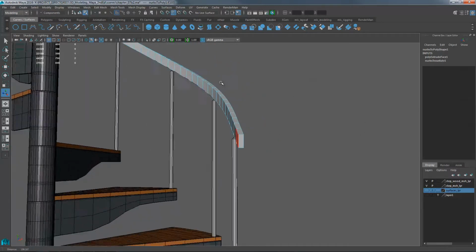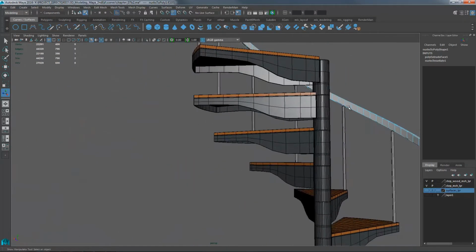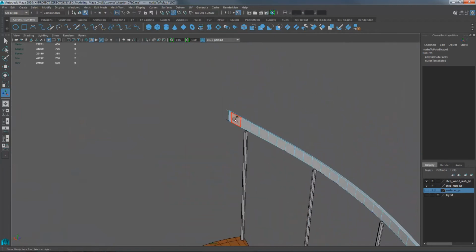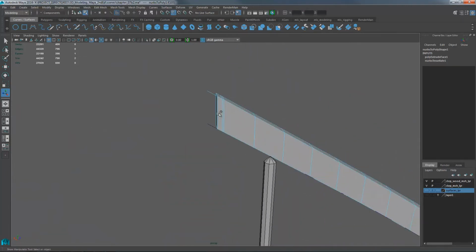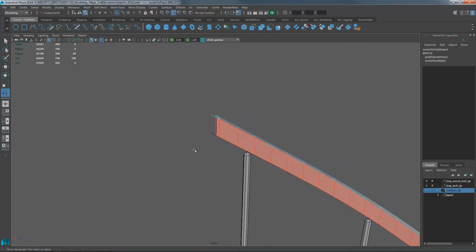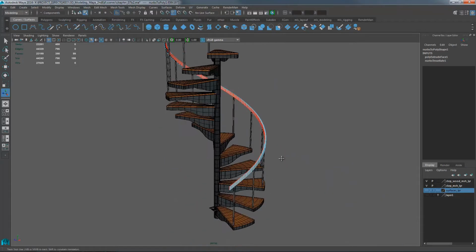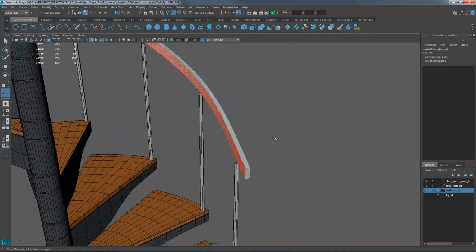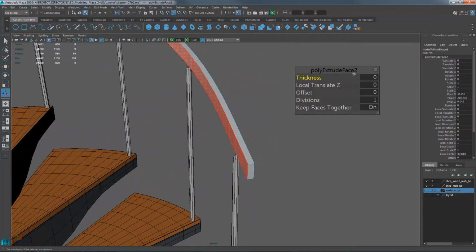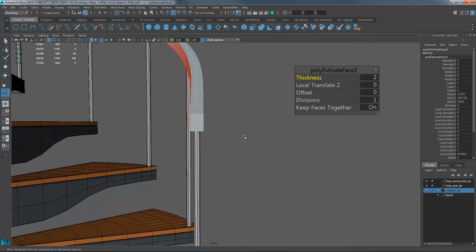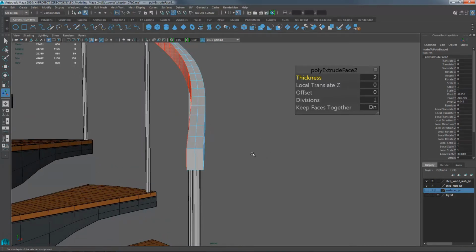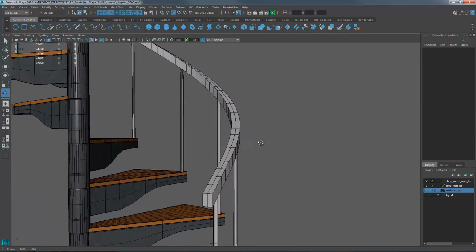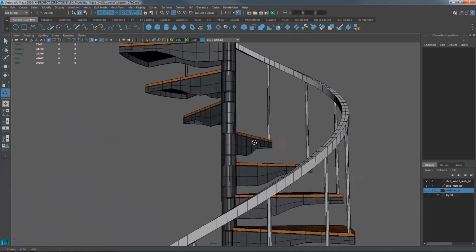Okay? And then select the inside. Hold Shift, double click. Yes. Get the inside and extrude that. Extrude that one. And thicken that one. Also 2 units. So you have a total width of 4. And notice how that has the correct twist all the way up.